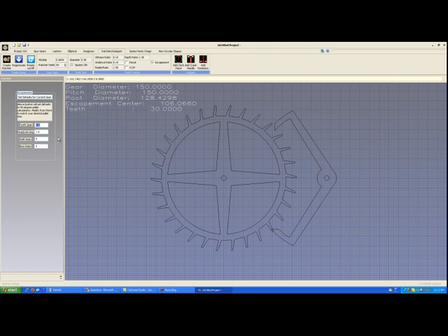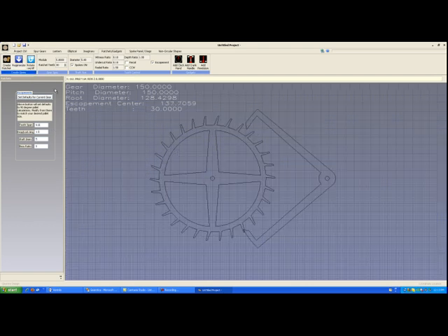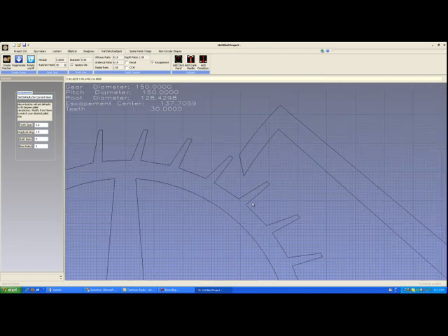Secondary to that, we can set a tooth span. Right now we have a 7.5 tooth span. This is very typical in the literature as well. But let's say we change that to a 9.5 tooth span and regenerate. You can see a couple of things have changed. Number one, the center distance has changed between the pawl and the deadbeat, and the pallet angles have changed. You can see that this angle of this line on the pallet is now no longer straight up and down.